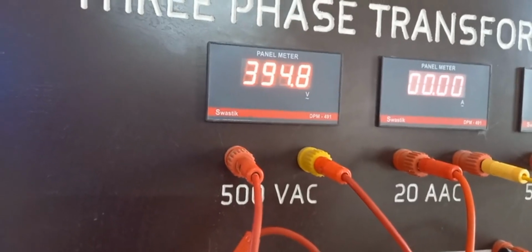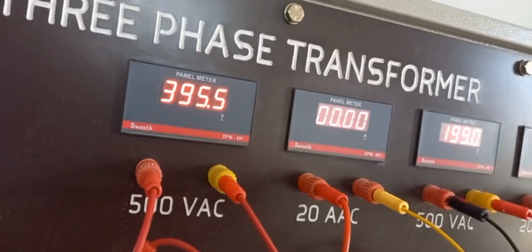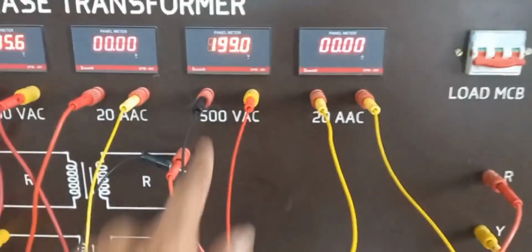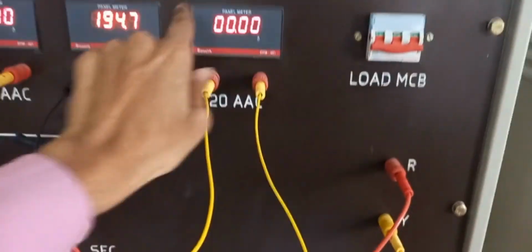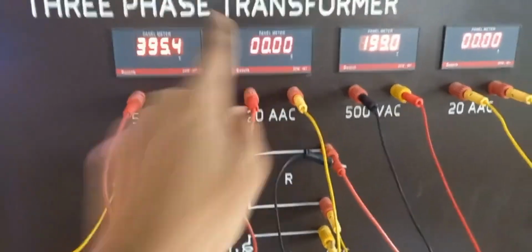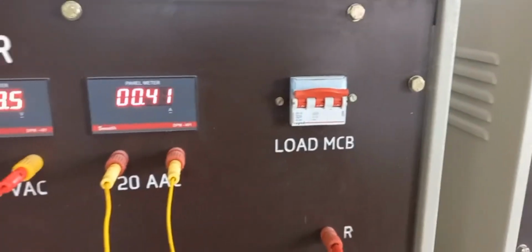I have taken 394.6 at primary side. Without load we got 199.2 here at the secondary side. Then I am going to turn on the load. So you remember, without load, the secondary side ammeter value is 0 and the primary side ammeter value is also 0. Then we are going to turn on the load.